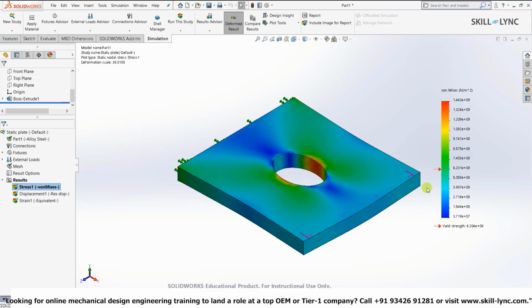And we have our result, but this time you'll be able to see that there is an extra arrow mark in the legend here. So what happened here? Since we are using a linear analysis, the results are valid up to the yield point of the material. The arrow mark shows the point at which the yield strength of the material was exceeded, and thus all the results above the mark are not acceptable. We will have to run a nonlinear analysis to get realistic values from the simulation.